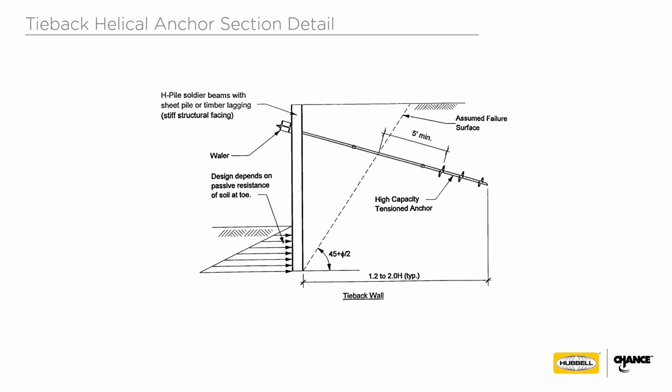What's important about your tieback, whether it be a helical anchor, is that it be beyond this failure wedge, so that the whole wedge can't fall over. Helicals are end-bearing elements, so what's very important about the tieback is that it has enough capacity for whatever load is intended to be on it as the wall height reaches maximum, and that it's long enough. If this last helical plate is stressing the soil that's behind the failure wedge, rather than the soil that's in front of the failure wedge, then your screw is not long enough, and the whole wedge could topple over towards the sea.